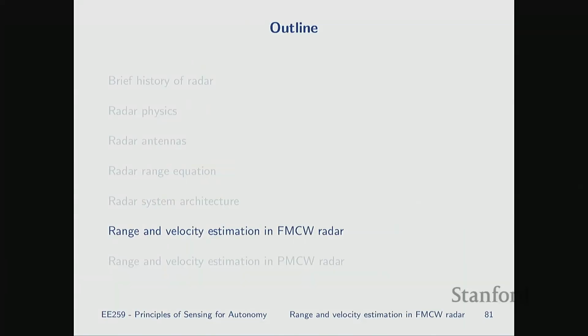Okay, so we're going to start with looking at FMCW radar DSP, and specifically how you can estimate range and velocity in FMCW systems. And then we'll do the same for PMCW. But again, remember, for FMCW we're going to go full depth, no stones unturned, in painful detail. PMCW, we won't go as much in depth.